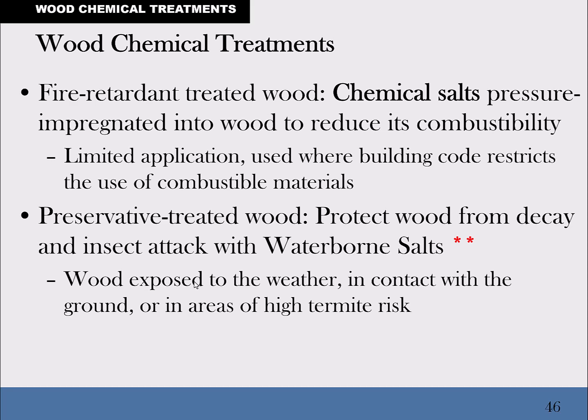Anyways, the whole thing here is with insects. They'll eat this stuff, and the pressure treated lumber, the preservative treatments we put in there, which are normally what we call waterborne salts of various kinds, they keep the bugs at bay. So wood that is exposed to the weather, in contact with the ground, or in areas of high termite risk, you have to pressure treat.